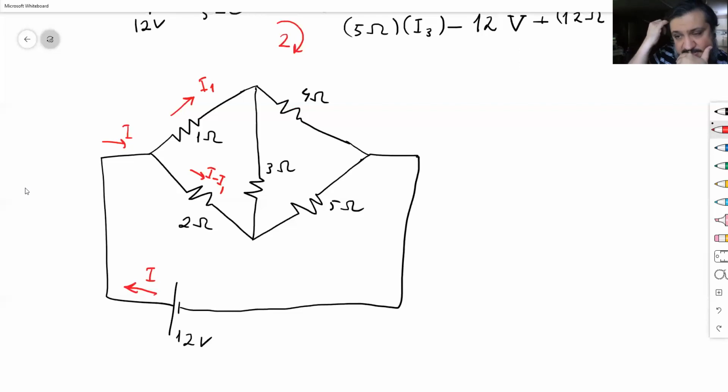All right. So what about 3 here? This current I1 will be splitting into 2 again. I'm going to call this I2. And this will be then I1 minus I2, using the same logic. I'm just applying Kirchhoff's rule directly. When I come to this junction, I have I minus I1 and I2 coming together to form the current. The current doesn't go, okay? I keep using that way. The charges go, just a figure of speech. So I minus I1 plus I2.